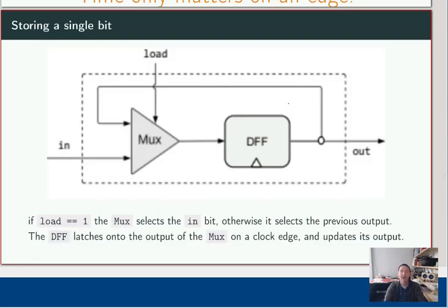So now, let's say we want to store a single bit of data on a clock edge, and of course later recall it. This is going to be the way we can store a single bit. We have some data input right here. It's going to go through our multiplexer because we want to be able to store that bit on a D flip-flop. So this is the input right here going into the D flip-flop. This symbol with a triangle, that means a clock.